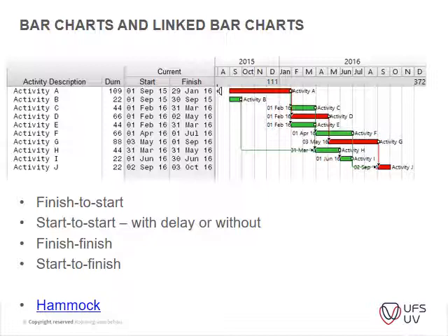So you might have a finish to start. This is all going to be explained in the next slides. With finish to start, whenever an item is done, the next item starts. But then you have scheduling allowed, so for instance, if the architect has finished up to a certain point, the engineers can start doing their designs.